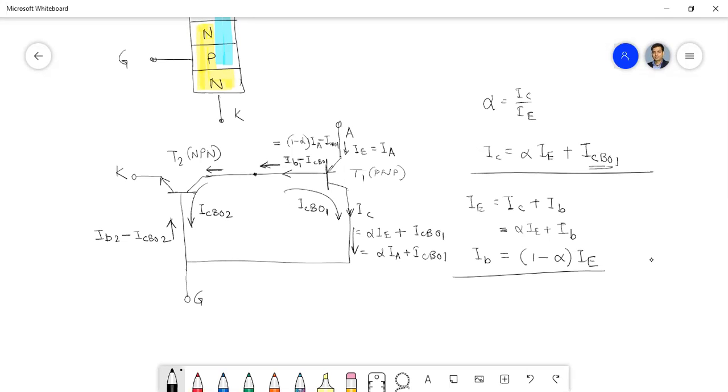Say? Sir, IC will be added, meaning the collector current. No, I am saying in terms of, so forget this, this transistor is over. So the matter of this transistor is done. Now come to this transistor. So for this transistor, if we see only this transistor, what will be this current? This current, what is that current? IC2 plus ICBO2, let me write.